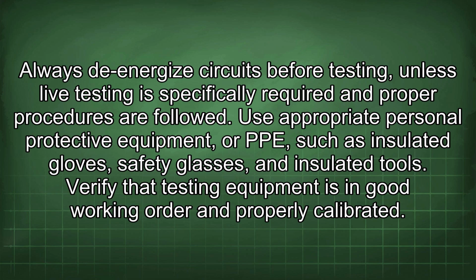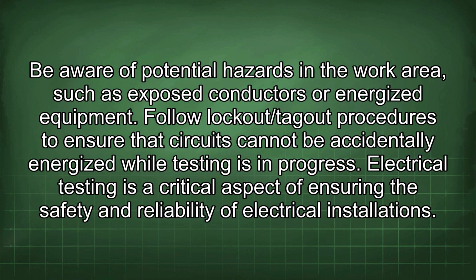Verify that testing equipment is in good working order and properly calibrated. Be aware of potential hazards in the work area, such as exposed conductors or energized equipment. Follow lockout/tagout procedures to ensure that circuits cannot be accidentally energized while testing is in progress.